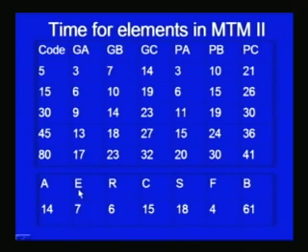For eye action, that is changing the axis of vision from one location to another, it is allotted 7 TMU, and R and C is the crank, rotating along a circular path for more than half of a revolution, 15 TMU. S is step, and for bend, 61 TMU time is allotted. Likewise, for foot motion, 4 TMU time is allotted. These are not related to weight.